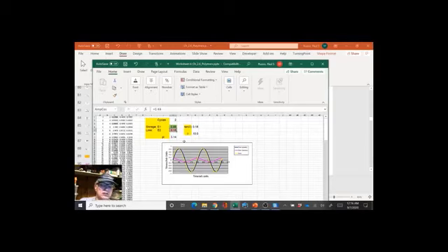What's actually done in practice is to calculate tangent of delta. Okay, so let delta be the phase angle difference between them. In this case, it looks like 10 degrees. Okay? And we look at this tan delta number, and let's run it up to see how that behaves. We'll make it be 0.995. So that's 99.5% elastic. Tan delta is 0. There's no phase lag. It's in phase. The response, the force, is in phase with the displacement. Okay?